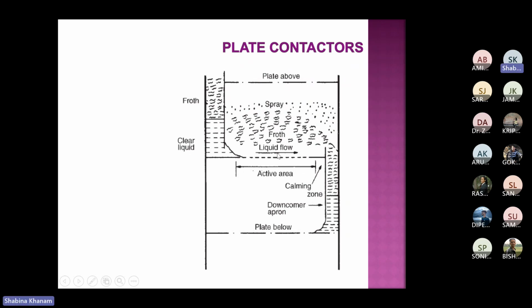If vapor velocity is too high, it will take liquid with it. It will push liquid from the downcomer to move upward. Please try and understand.